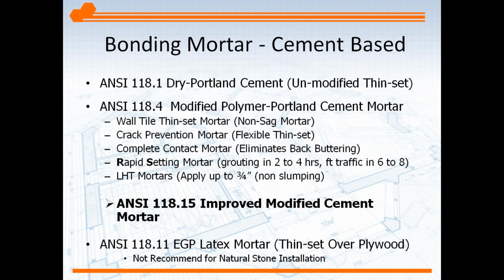Because again, this is an AIA presentation, I also want to cover all the bases. A 118.11 is a latex mortar for thin set over plywood. All right, it's not recommended for natural stone installation, and every manufacturer has this product as well. It's not as talked about because with plywood we have residential situations mostly, but there is a product for thin set over plywood, and it is the ANSI 118.11.